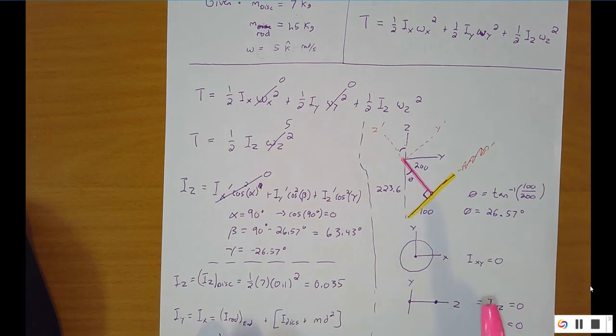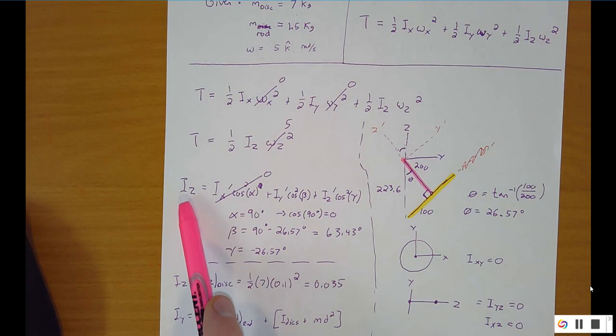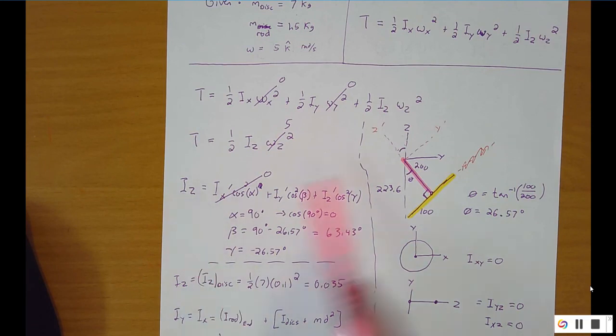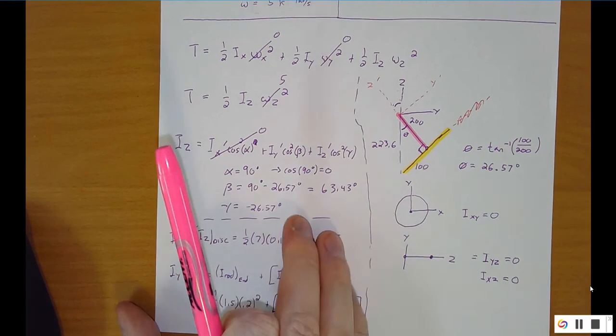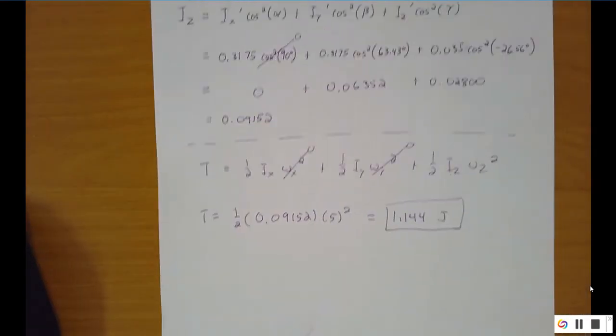And then proceeded to use our mass moment of inertia translation from a z prime to a z. And so remember, this equation has 3 other terms, but they're all for our products of inertia, which are 0 due to symmetry. Put them together and solved. Hopefully that helps.